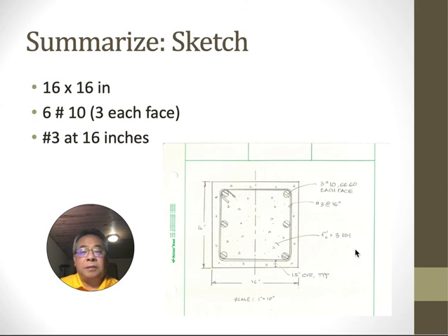And I actually drew this thing to scale, and you should do something like that. And because we went for 2% steel, that fits. And the last thing I should check is this distance here. Let me draw. This distance here, that needs to be less than 6 inches. And I'm almost certain that distance is less than 6 inches. Because this is in a corner, so that's safe, it won't buckle. That's in a corner, that's in a corner, that's in a corner. This one is not. And the rule is, if you're not in a corner, you have to be within 6 inches of a neighbor. And so let's see, we should check it right now.